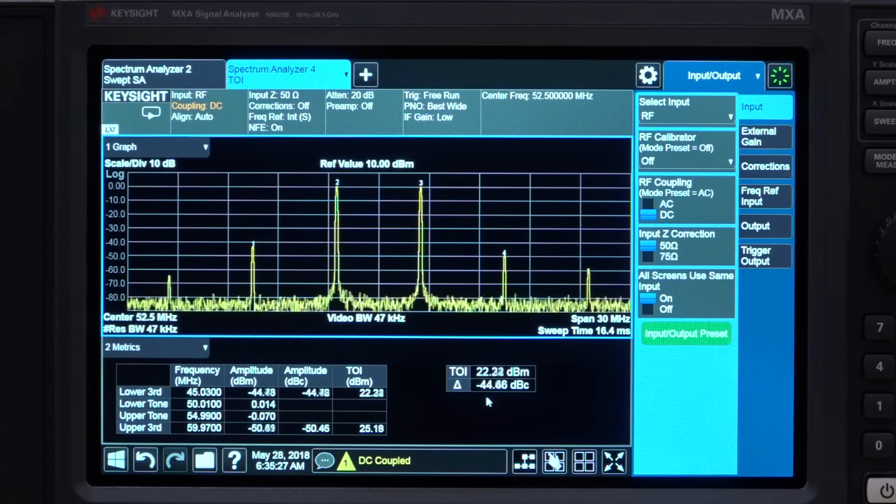If you were to upload your own arbitrary waveform in each channel, I suspect that the results would perhaps be better, at least based on what I saw from the THD of a single channel. But nonetheless, this is what we have to deal with, and you have to see if you're able to generate per channel these higher frequencies two-tone at the same time, which I'm not sure is possible, because in pure arbitrary waveform mode, you're not able to create a total custom waveform that occupies all the way up to 500 megahertz, as I explained earlier on. So having said that, you would have to deal with this type of nonlinearities.